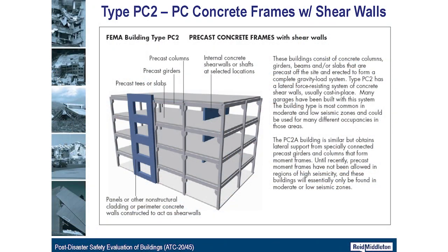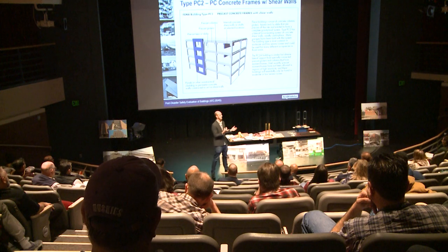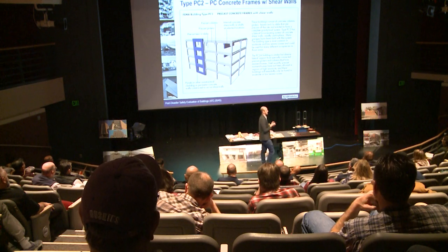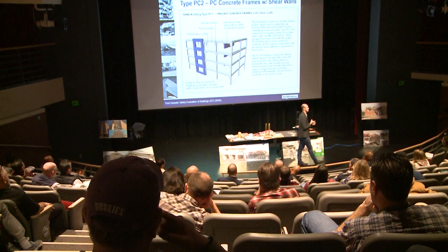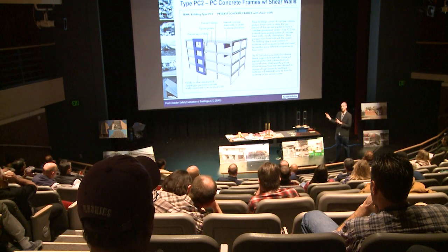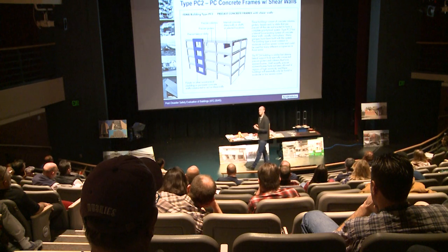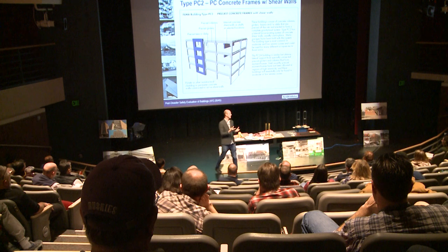That's tilt-up walls. The last is precast concrete frames with shear walls. Maybe just generally talking about which types of buildings are considered ductile and non-ductile. So is reinforced concrete construction ductile? It depends on the detailing. Hopefully we hit that home. What about wood framing? Generally speaking, if things are tied together pretty well, it's ductile. Wood framing can be non-ductile, like those videos we saw from Japan. What about steel? Ductile or non-ductile, generally speaking.